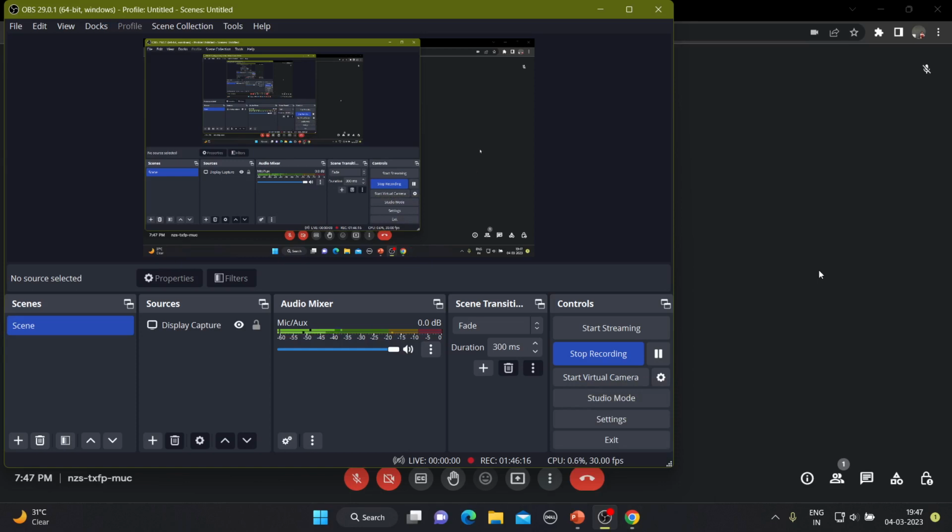This also you can get from the lecture slides, how delta by x is related to the Reynolds number. This is a direct relation. If we have a laminar boundary layer, how is this delta by x related to the Reynolds number? Delta by x is equal to 5 by root over Reynolds number, that is Rex, sorry. So we know that delta by x is proportional to Reynolds number to the power of -0.5. You can directly get these from the lecture slides, the boundary layer theory for this laminar flow. From there you can get this relation directly. Okay, so now let's go to the next question.